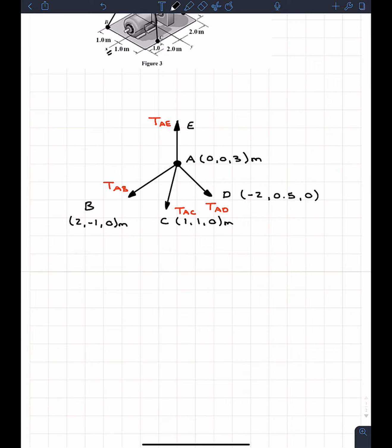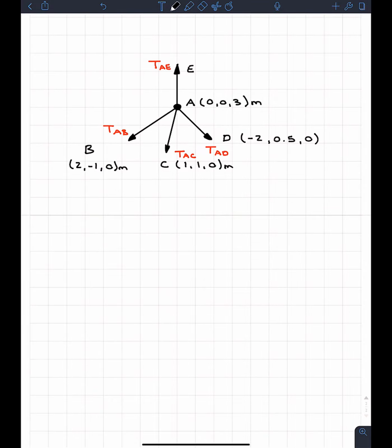The only problem is we always know that for 2D, if we're finding a component of it, let's say the X component, it's typically F times cosine of theta. And that cosine of theta will give you a number less than or equal to 1. Say it's 0.6. So just for example, we can say that Fx is equal to 0.6 times F. And this is great because then we can throw that in our sum of the forces in X. But the only problem that we have for 3D equilibrium is if we look at this 0.6, it's that coefficient in front of the force.